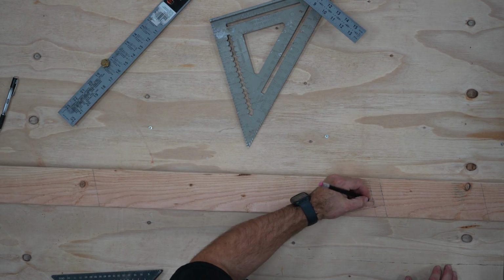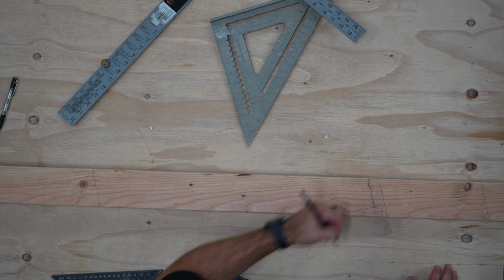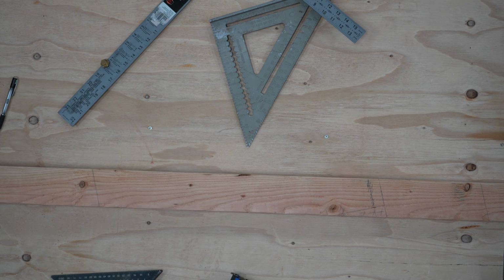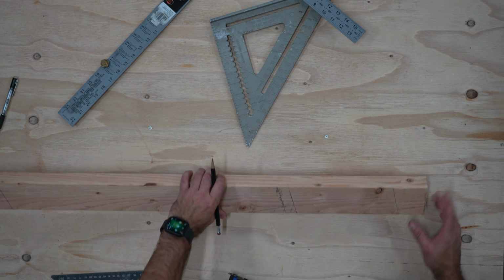Now this was just a reference line, so I make sure to scribble it out so I don't accidentally cut it. I still need to cut the original line, I just couldn't measure the seat height from there, as it would then be too tall once I set it in place, and it wouldn't plane out with the common rafters.